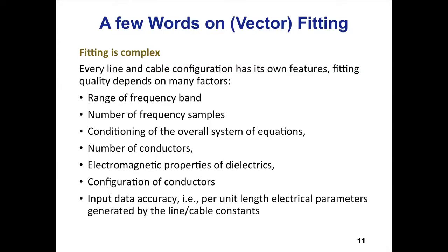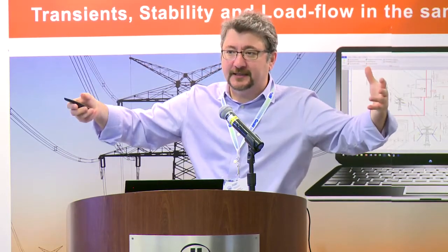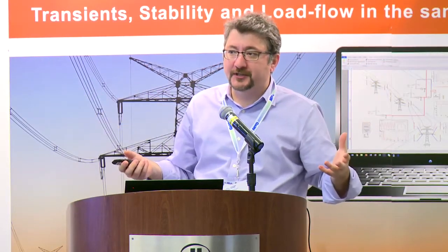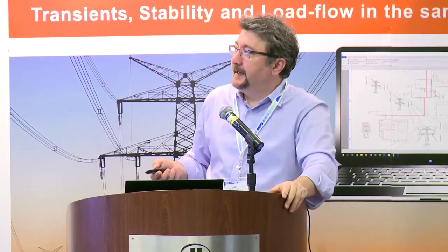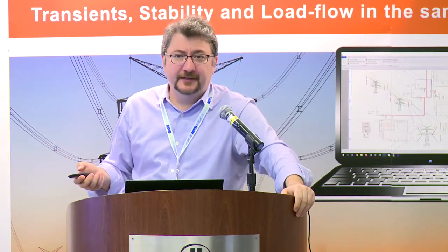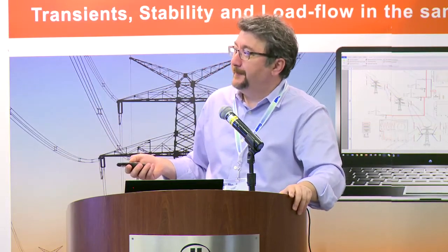Concerning fitting, I would like to add a few words. Fitting is not easy, okay, because you have a multi-delay system. So you have a range of frequency band. This impacts the fitting. This impacts the numerical conditioning. In the same matrix, consider you have a transfer function. You have 0.01 hertz, and you have megahertz to the power of something, depending on the order of fitting. So this is not easy. How many frequency samples do you have? Is it overdetermined? Is it underdetermined? All these things have an impact.